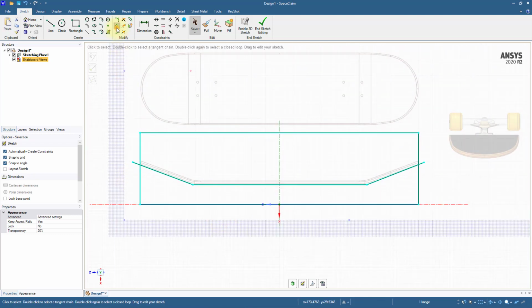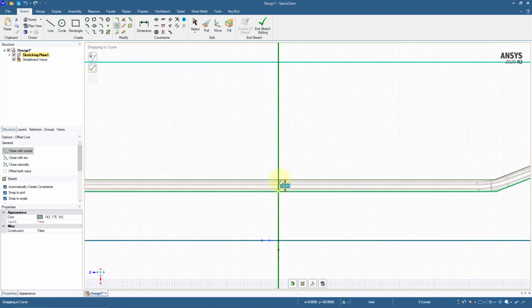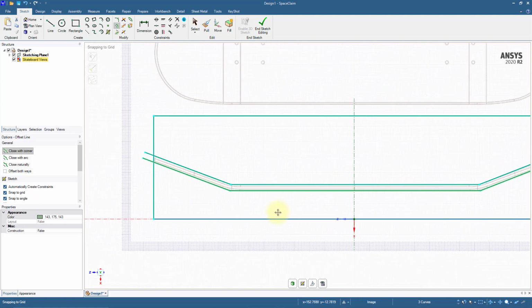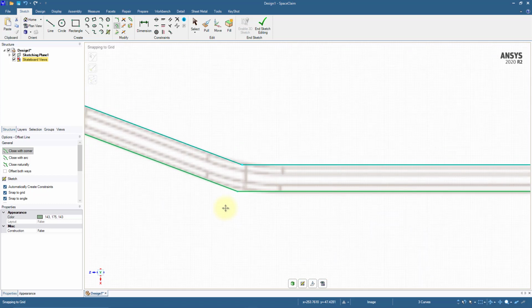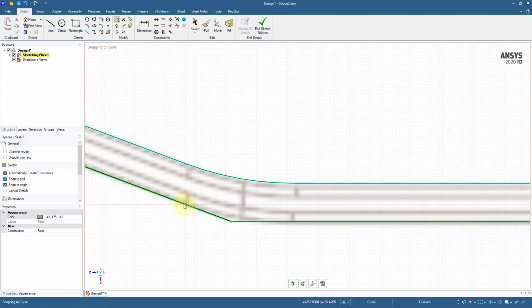Use Offset Curve to create the outline of the top profile of the skateboard using the 3 lines we've just finished sketching. Now, add a radius to the vertices. We'll have to use our best judgment for many of these dimensions. Think about how you would design a model. Would you use many random and arbitrary dimensions, or would you tend to go for symmetry and even uniform numbers whenever possible? If an area you're tracing measures 103 millimeters, but 100 millimeters seems reasonable when compared to the image, use the nicer looking value.